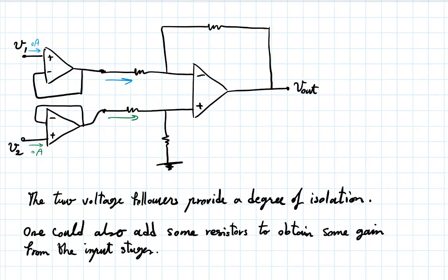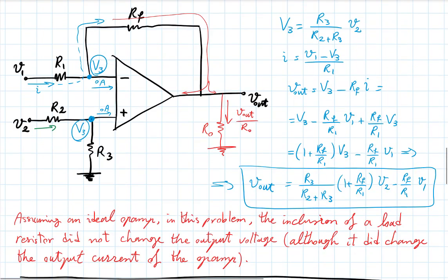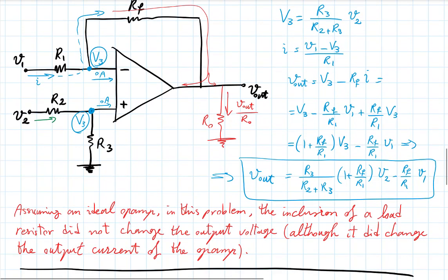Yes, exactly. So the question is, will the op-amp provide anything that the circuit needs? And the answer is, again, assuming an ideal op-amp, or for a real op-amp, assuming that you don't ask to go beyond this range, then yes. Like in this example here, if I did not have a resistor here, the entire blue current would go to the output of the op-amp, and the op-amp would accommodate it.